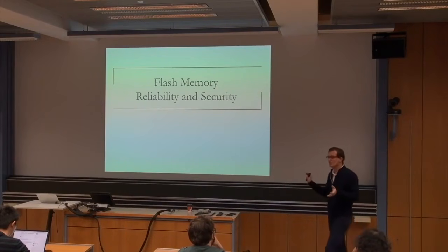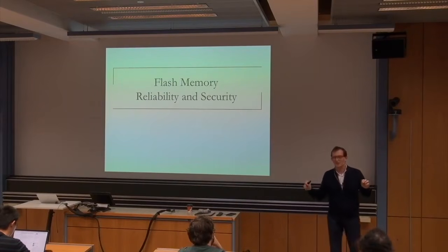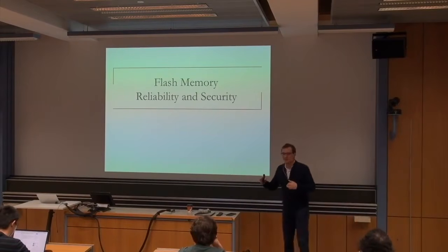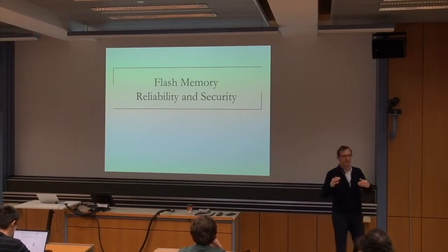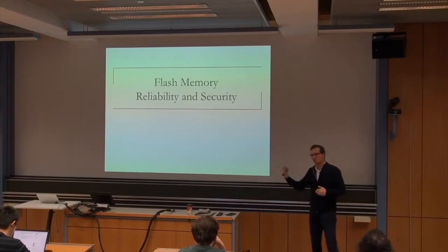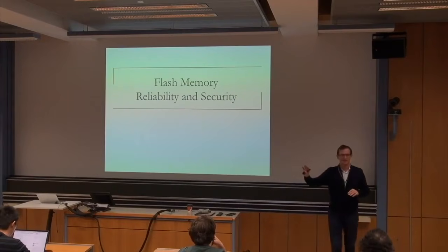But there is no mechanism to erase a single page. Erases are done only at the block granularity. And this is a trade-off that was made for cost reasons, because erases are actually extremely expensive. As a result, flash manufacturers said, we're going to do erase at the block level. And as you saw, blocks are 256 pages, right? And you do erase at the block level, but you want to modify only that page. Now you have a problem.